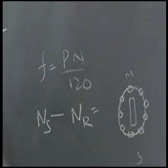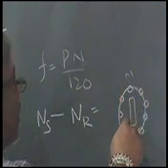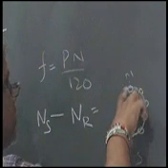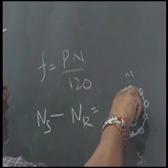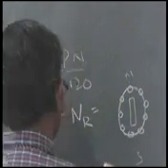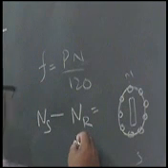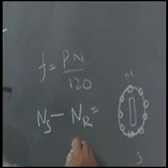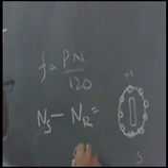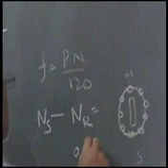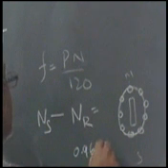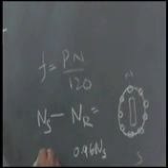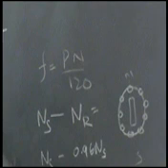That will be the synchronous speed of the stator magnetic field minus the speed of the rotor. Say this Nr will be 0.96 Ns. So the difference in speeds will be equal to 0.04 Ns.